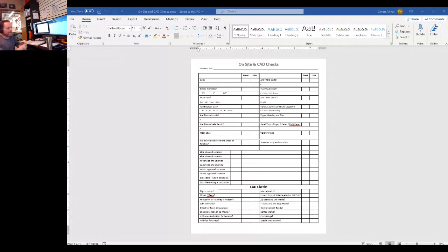When you have a 3D model, you can type a command just called DIR, or direction. So you can select that model and hit direction, and it'll give you a bunch of arrows. And really what you're doing is you're checking the direction of the model. When you flatten that model, you need to know what direction it is. Are you looking at the inside or are you looking at the outside?